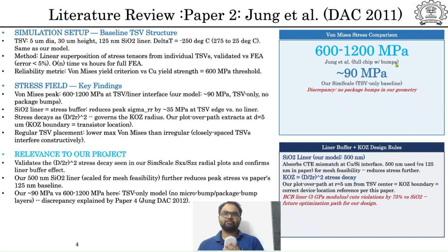So as we can see, in Jung et al. the stress ranges from 600 to 1200 megapascal, but in our model we considered 90 megapascal. This difference is because we considered only the TSV, while their work includes the full chip package effect. Some design insights: increasing the liner thickness reduces the stress. KOZ defines a safe region for device placement. Softer material like BCB further reduces the stress. So overall, the paper shows that TSV stress strongly affects full chip reliability, and proper design optimization is necessary.